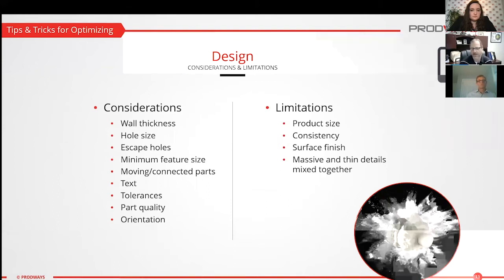most of this information is coming from the polypropylene material. Wall thickness. Yes, all of these are part dependent, but about 0.5 millimeter is what we recommend as a service provider that's been in this industry for over 2 decades. 0.4 millimeter, 0.5 millimeter. Hole size. When you start getting down to 2 millimeter diameter and under, it starts to get challenging. There'll likely be some secondary ops to qualify your hole.